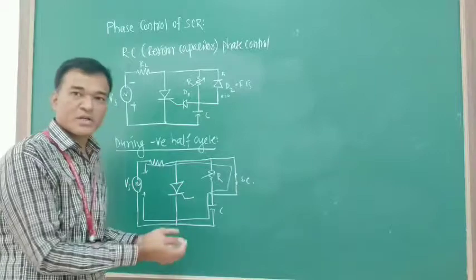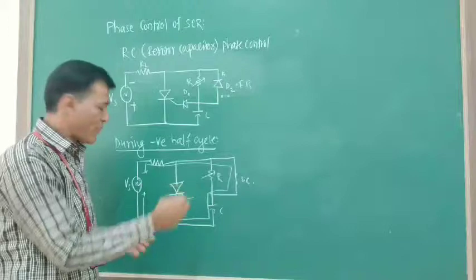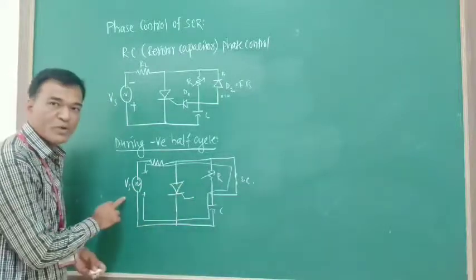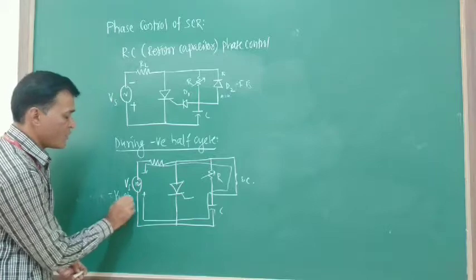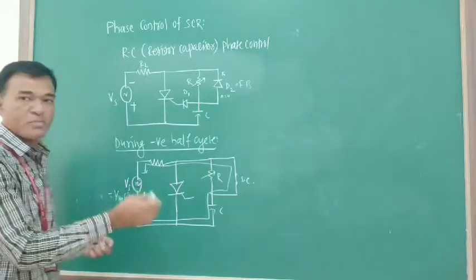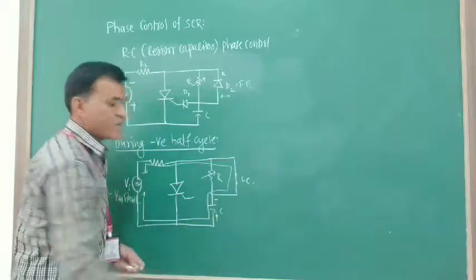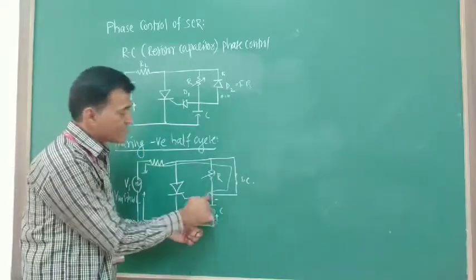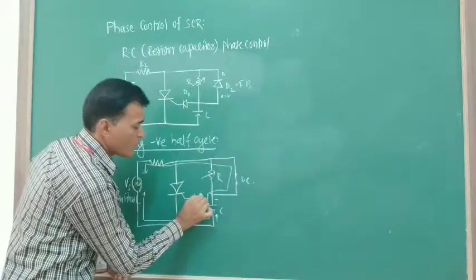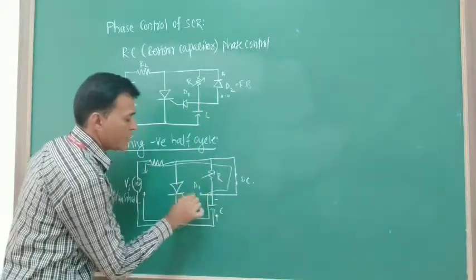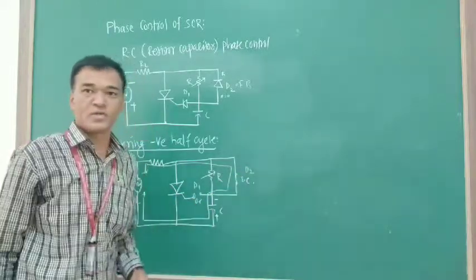Right? So the capacitor slowly charges from 0 to the maximum value of the input voltage. We know that the input voltage is Vs, which is nothing but Vm sin omega t. So it reaches its maximum value with polarities plus downside and minus upside. As this minus is connected to the anode of diode D1, this diode is open circuited, while diode D2 is short circuited.